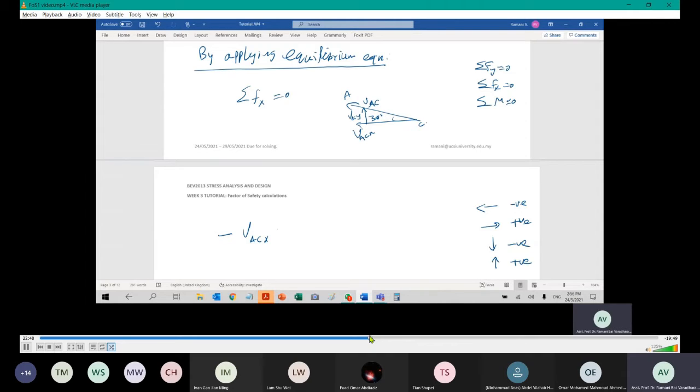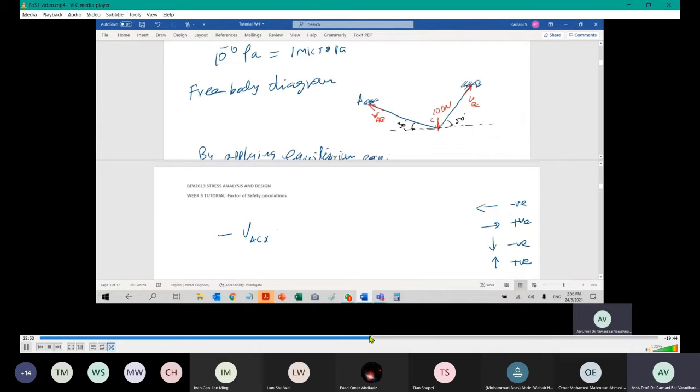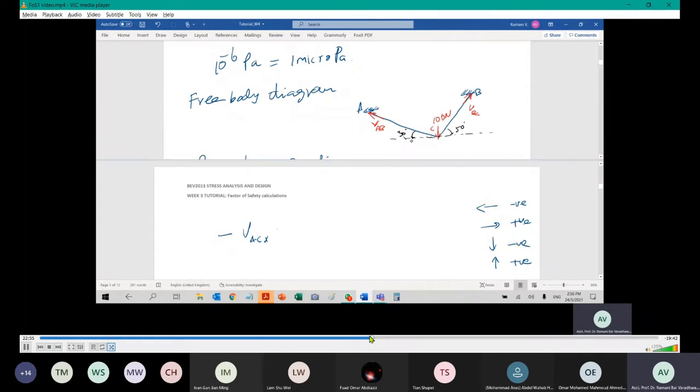I need to do this reaction. Come on, any other horizontal reaction acting on it? Go to the member. I have taken this component due to this reaction. Now we need to take this component due to this reaction. Let me take this one, point C. Please check if I make any mistake. Angle is 50 degrees, right? And then similar to the last time, we have to mark the reactions, how they are vertical and horizontal, resolve into vertical and horizontal so that you can resolve them easily.